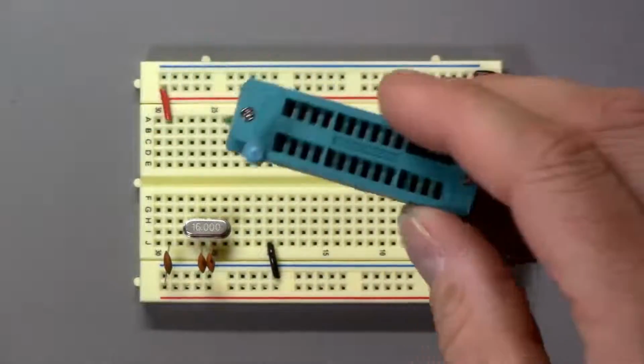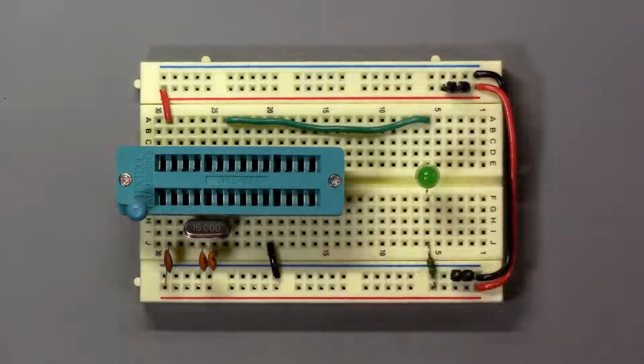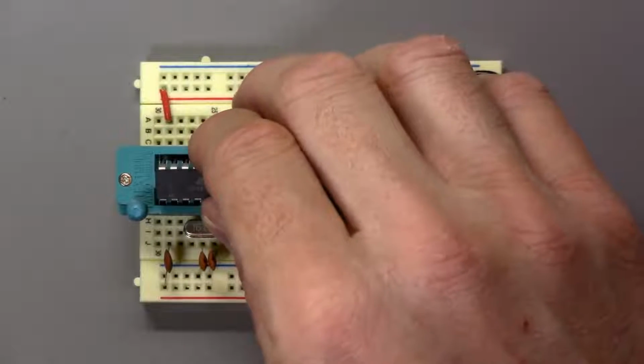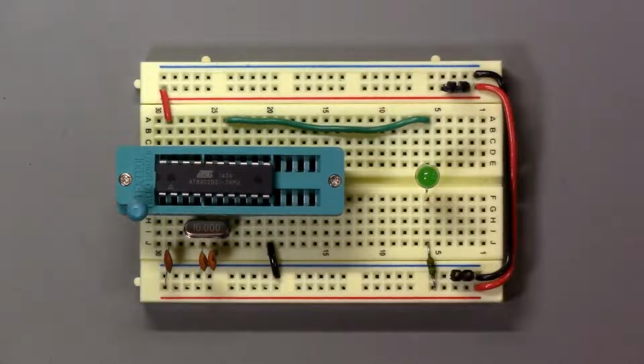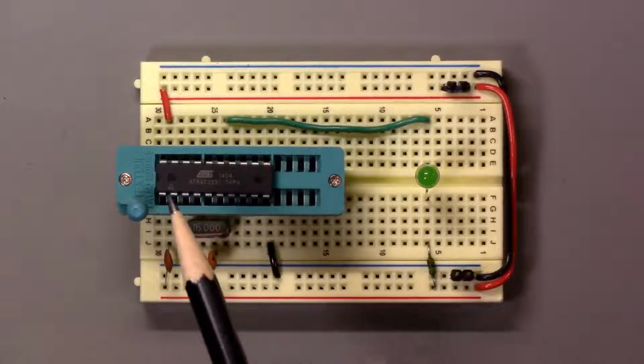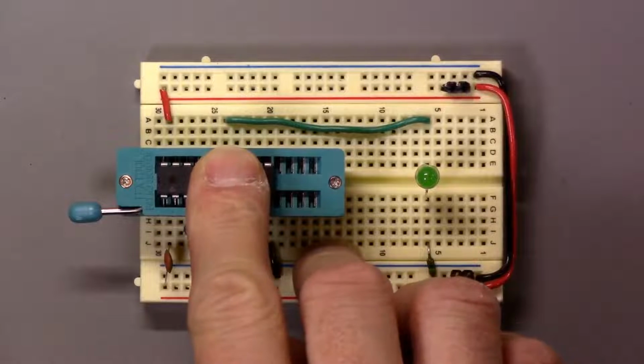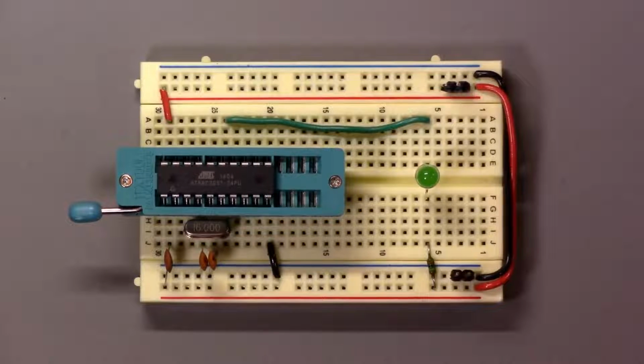I've soldered some header pins onto the ZIF socket, and basically that's going to be useful to prevent the pins from breaking as we repeatedly put the microcontroller in and take it out as we work on the firmware and program new firmware into it. So this is the actual device. So let's engage that, and so now we just need to apply power, so give me a moment.